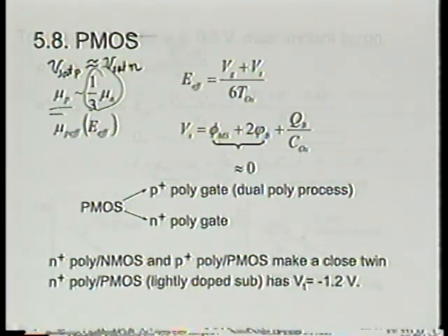At some point, more than 10 years ago, people used to predict that when channel length gets very small, N channel and P channel IDsat will become nearly identical. Can you see where that kind of projection would come from? It comes from the idea that eventually current will be determined by saturation velocity, not determined by mobility.